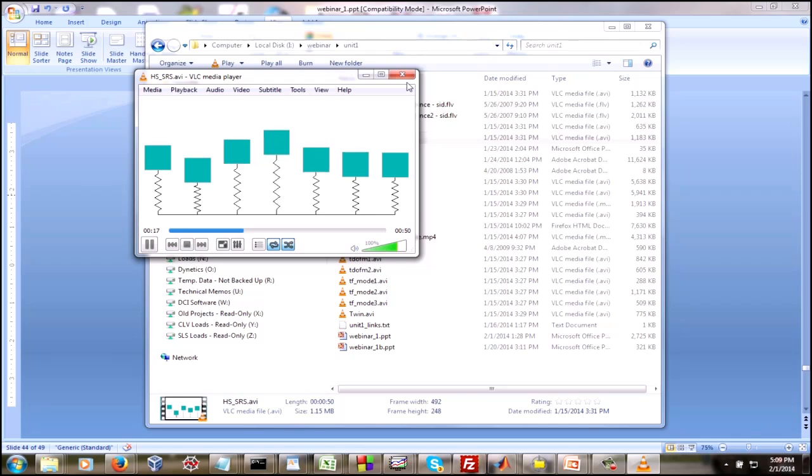Okay, what else do we want to say about these? Well, in many cases as we go through life, moderation is a good thing. But in this case, a moderate natural frequency would be a bad thing for this particular half-sine pulse and this particular family of natural frequencies with their common damping ratio. So in this case, we'd either want to be one way or the other. We would either want to soft mount our system, maybe via isolators, or we would want a very stiff system.